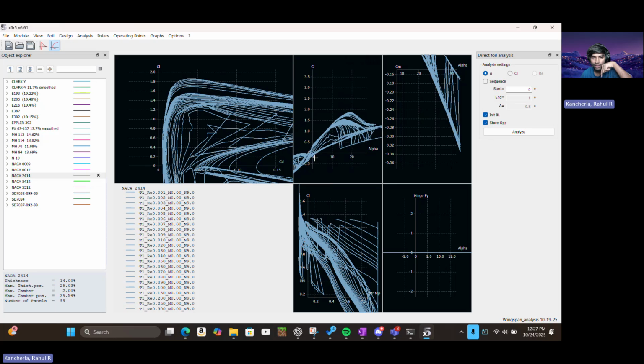However, this one is, I guess, fine if you're just building a plane. It's saying that at 0 angle of attack, the airfoil will have no coefficient of lift, which basically means no lift. In some cases, that's bad. In some cases, it's not. It really depends on what you want out of your plane.